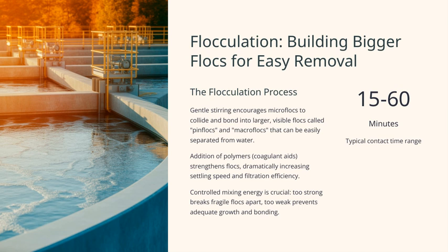So, in summary, effective flocculation relies on gentle, controlled mixing, the strategic use of polymers, and appropriate contact time to build bigger, stronger flocs for easier and more efficient water treatment.